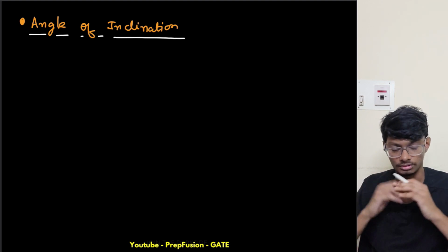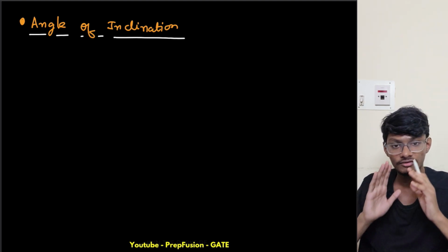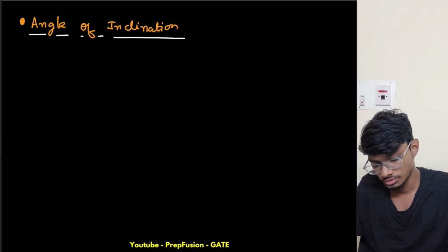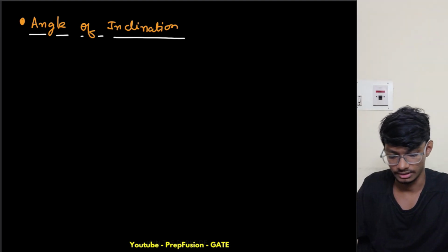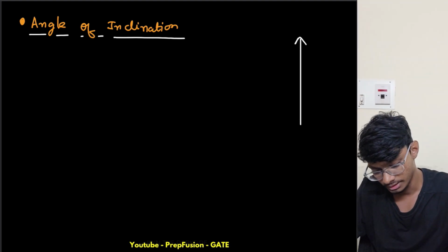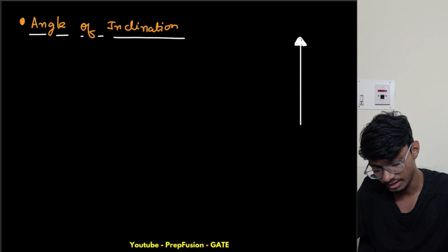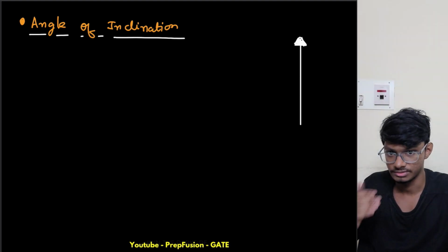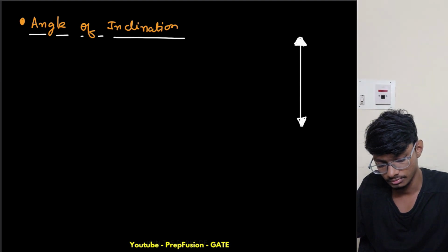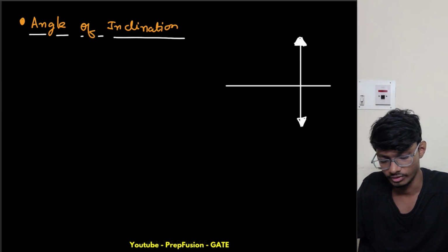So now we will come to another important point. After this, what we learned was the angle of inclination. So what is my angle of inclination basically? For the angle of inclination, let me draw the graph and put a pole location. This is for the underdamped system only, but this can work for a few other types of damping also, okay? But this won't work for overdamped, right? Overdamped it won't work.